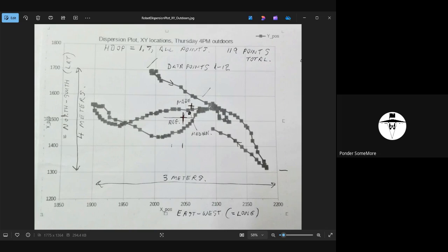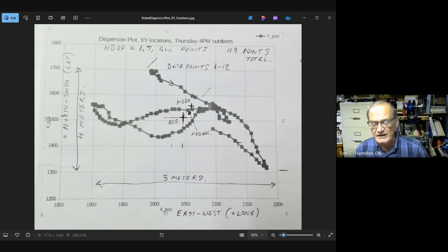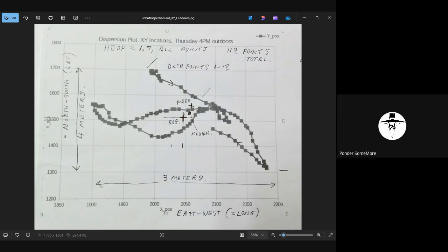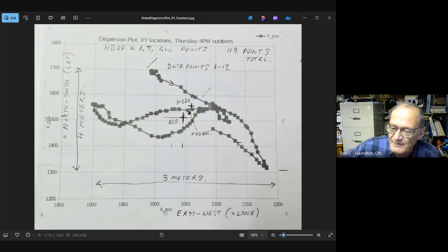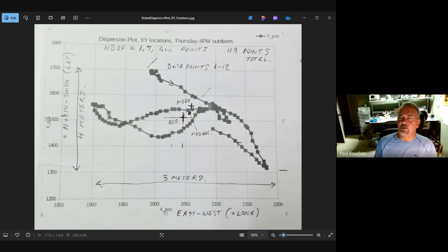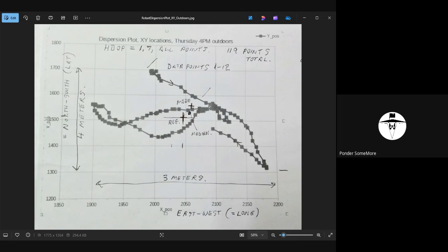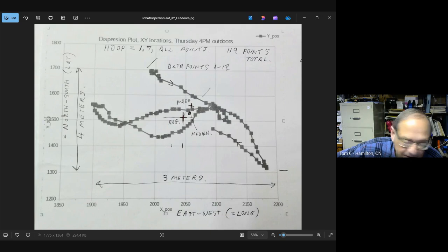I don't know that you can just stick an L1, L2 antenna on a receiver that only receives L1. I didn't think so, and I don't see or read any technical discussion of an antenna that would be suitable for the receiver I've got. Yeah, those normally come integrated, don't they? Well, they're separated by about 3 inches of cable. Oh, really? Are you sure your receiver is only L1 and not L1, L2? Because nearly all of them are L1, L2. This is a 6. The 6 is definitely L1 only. Okay. In fact, you have to get up to the 9s, and only some of the 9 models, before U-Blox data sheets mention that they're L2 capable. Really?